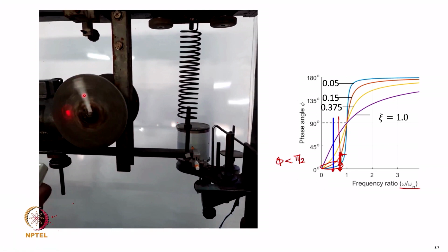That basically is aligned with the unbalance that is located. So, this unbalance is going to indicate that the force is acting in this direction. As the disc rotates, the reflective tape here also rotates and shows the direction of the force acting on the disc and therefore on the entire beam.